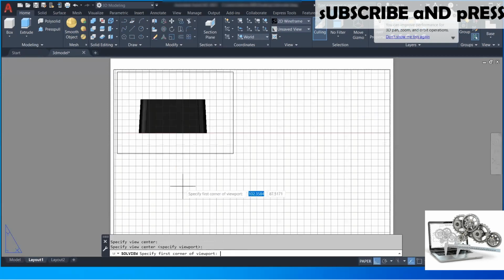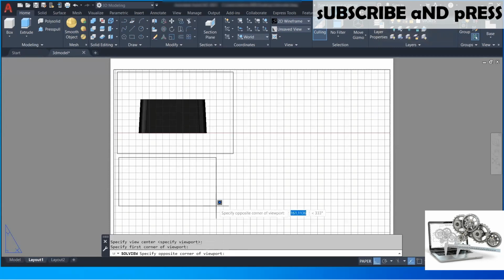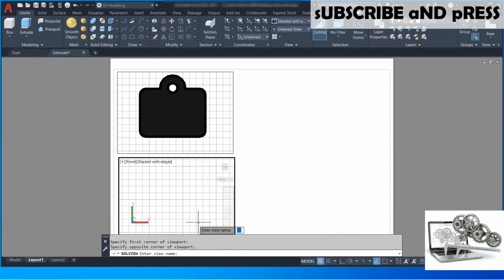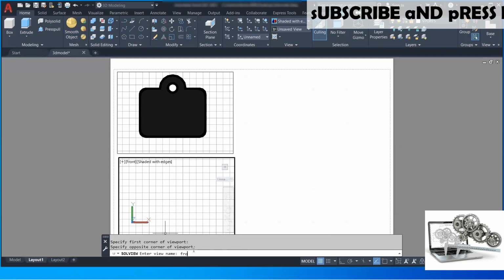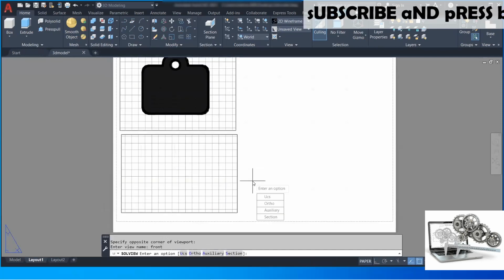Now it is again asking for the view center. So click on the downside, press enter. It is asking you for the first corner, then give the other corner. Now it is asking for the name. So name it as front view. Okay, done. Now after that it is asking for another view.